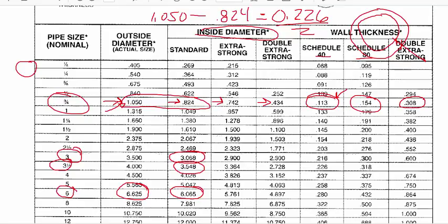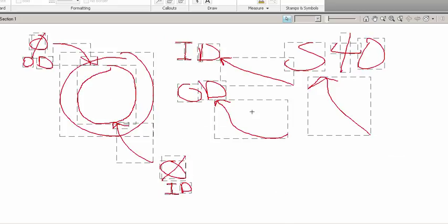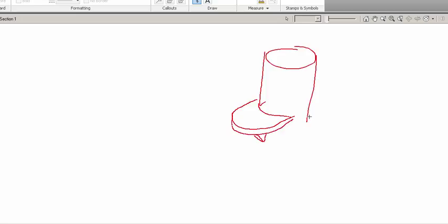For example, let's say that we were going to use a steel column that was a pipe, and we wanted to make a gusset plate that hangs out over the pipe to set a beam on. So we're going to do a gusset down below, a triangular plate down below. But as you see, I have to cut out my plate to match the curvature of the radius of the pipe. If I just tried to cut it square, what's going to happen?